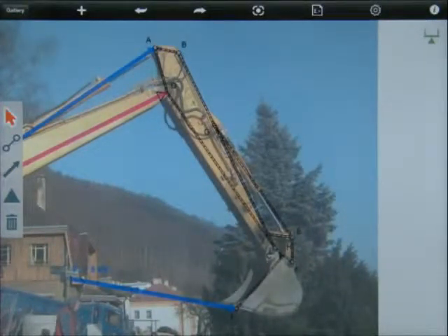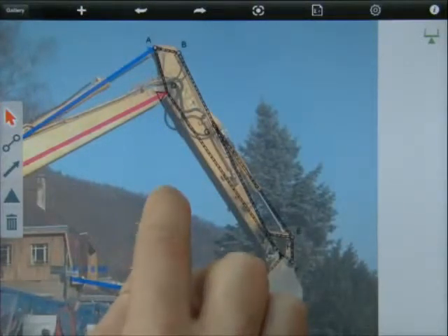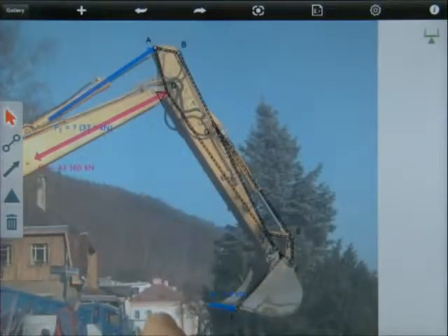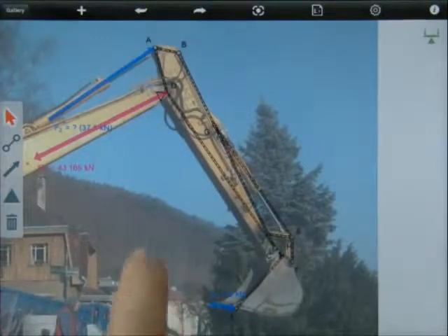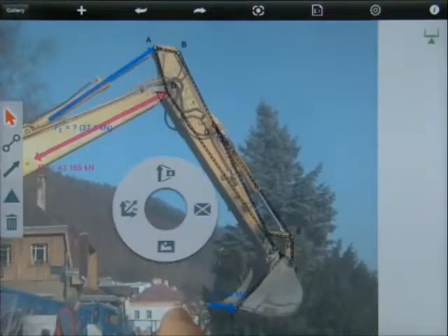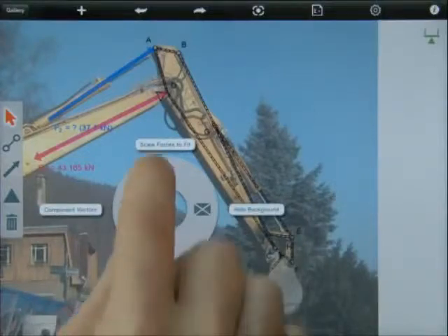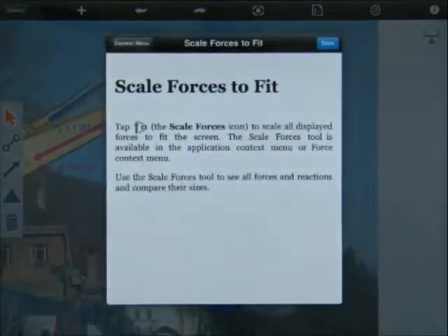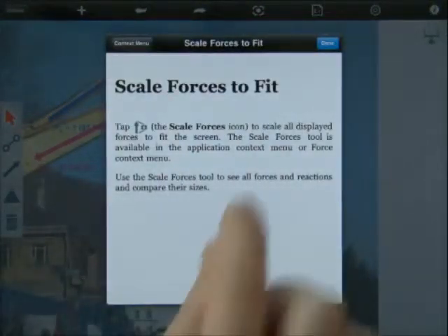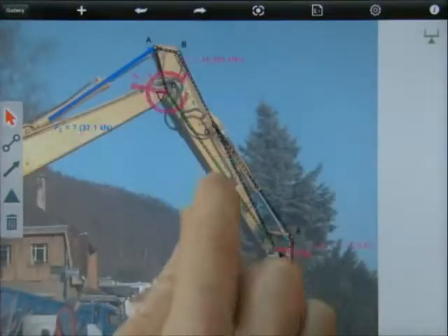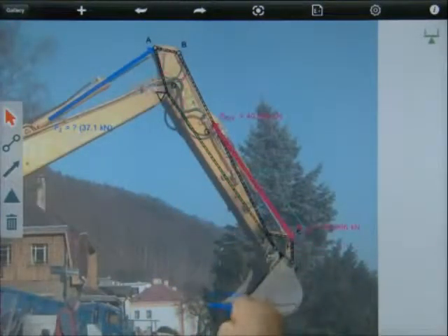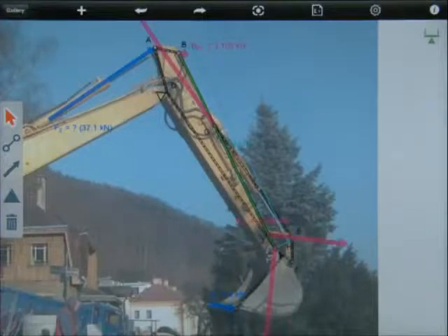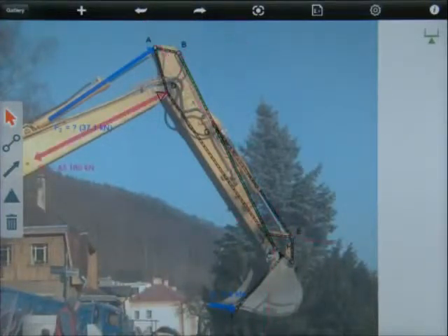The degree of freedom indicator changes to an equilibrium, and the reaction forces are displayed at the supports. The force vectors are scaled. This is relative to the graphics only. Tooltips display for each command briefly. Tap a tooltip and find out more information about that command. You can use your select mode to query individual members and see their reaction forces.